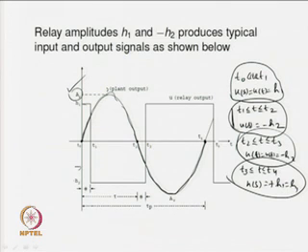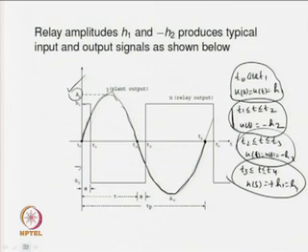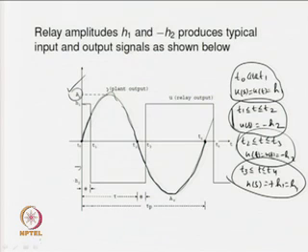So, analysis will definitely give you exact expressions for this output. Why will those expressions be exact? Because we are not making any sort of approximation in our analysis; rather, we are employing the state equations for finding the expression for the output, and these are exact expressions without any approximations, unlike the describing function case where you approximate the relay by an equivalent gain. So, no approximations are used in the analysis; therefore, the expressions we get will be exact.